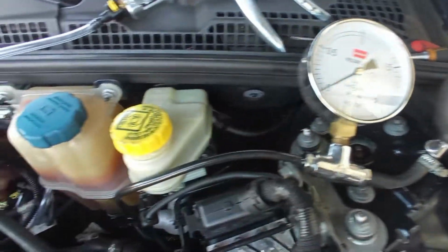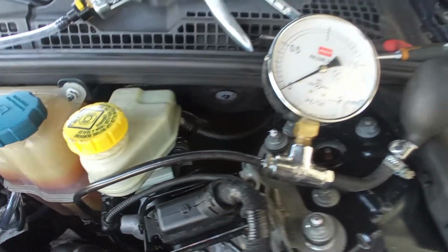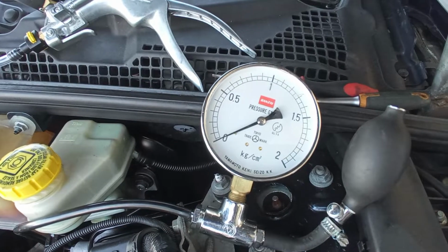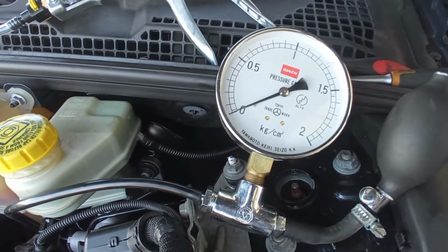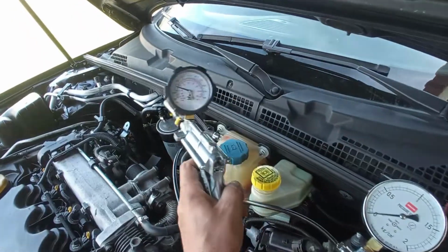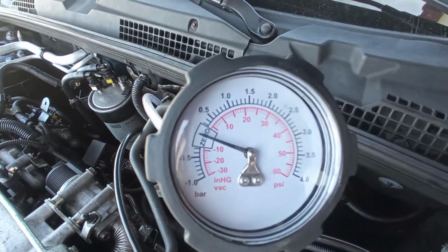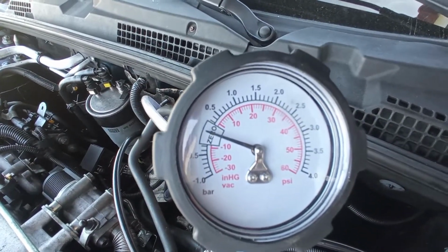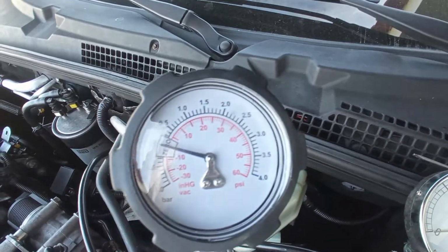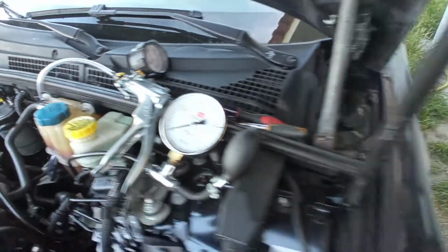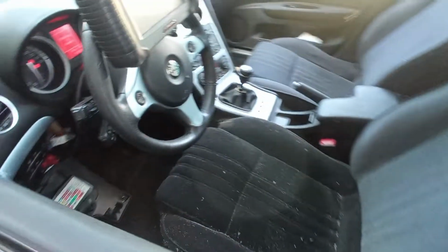Meanwhile, while that is charging, I can see the pressure on the exhaust. It's very low, so maybe I have almost a clean filter, because at idle I have nothing, or virtually nothing. So as you can see, the gauge on my gun is very difficult to read. Not very difficult, but the amount of pressure that I want to put on the sensor is easier to read on the diagnosis machine.